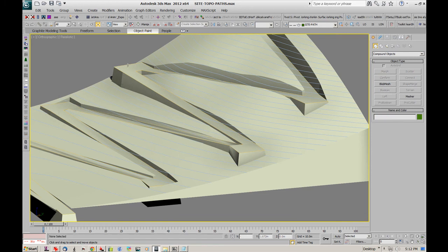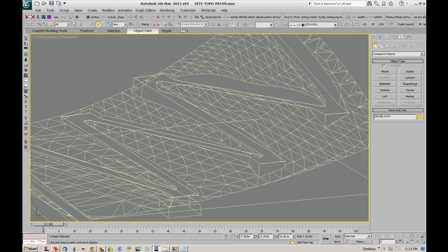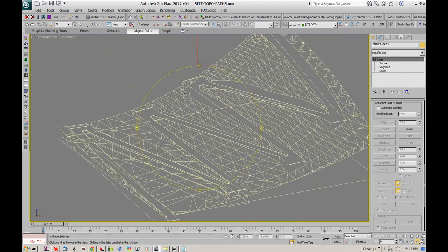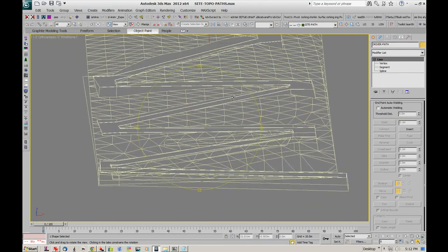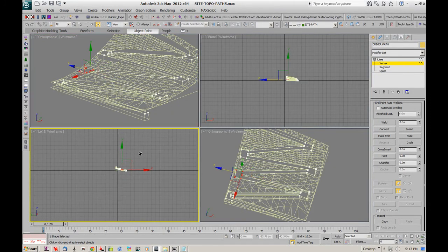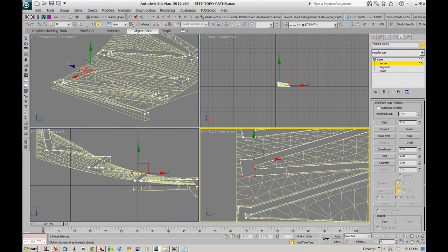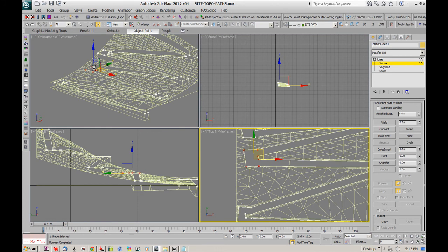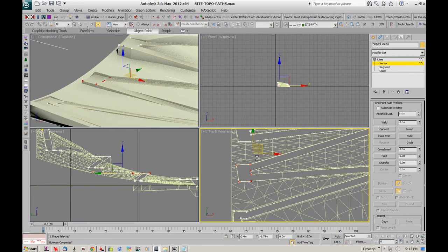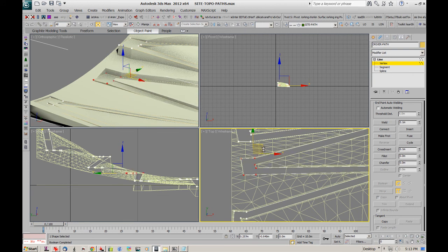There's a couple of things that we can do. I might just hide this. There's a few floating splines, but because we used the reference clone, we can make adjustments to the path, and if we're lucky it won't crash, and it'll update the topography. So say we wanted to, let's go into a top view. I wanted to move this around a little bit. I can drag that and I'll shade that view so you can see it a bit better. And you can see the Boolean's updating, depending on how crummy your laptop is, in pretty close to real time.